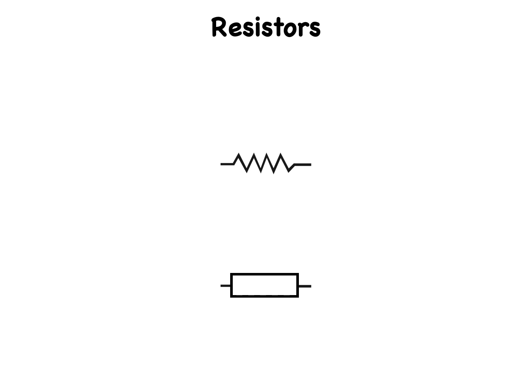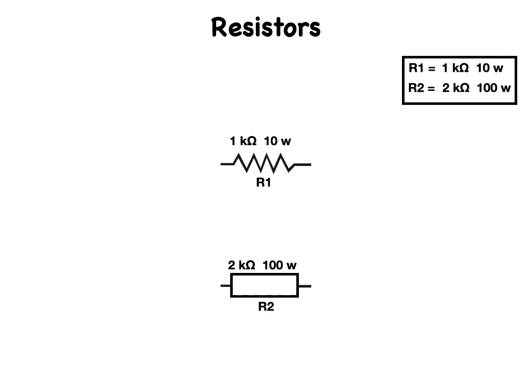The schematic symbol for a resistor, all by itself, tells us nothing about the ohmic value, or anything else about the component such as its power rating or physical construction. Various specifications for the component can be written alongside the resistor symbol, but these details might also appear in a separate components table and referenced by an alphabetic or numeric designation printed next to the schematic symbol, such as R1, R2, R3, and so on. You can usually determine the ohmic value of a fixed resistor by looking at the colored bands or zones on it. More on this later.